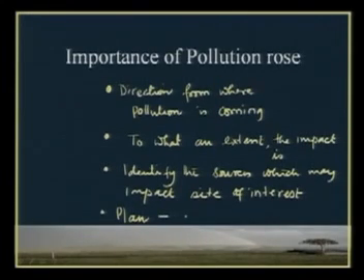a pollution control which can be season specific, because you see the wind direction changes from season to season, and so will the impact of sources. In winter, most of the pollutants may come from the north, and in another season they may come from the east. So you can say, well, when it is summer, the pollution control must be effective for the pollutants generated from the south. This way you can make very useful decisions and contribute to pollution control.